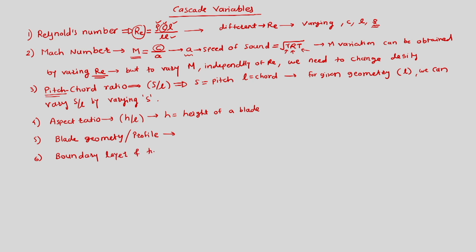And turbulence. We have seen here that the cascade receives the boundary layer from the contraction and the test section. It is invariant: however perfect a contraction we implement, we would still have a certain thickness of the boundary layer which is received by the cascade.